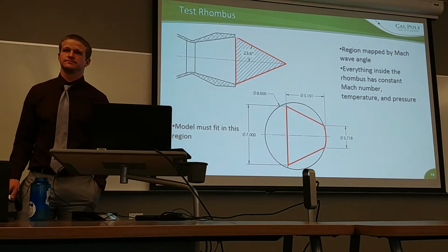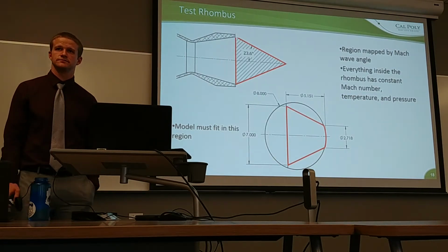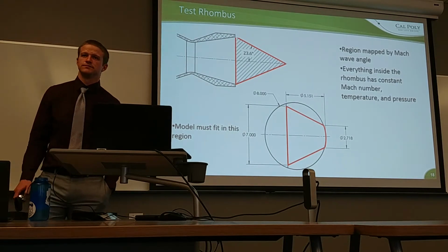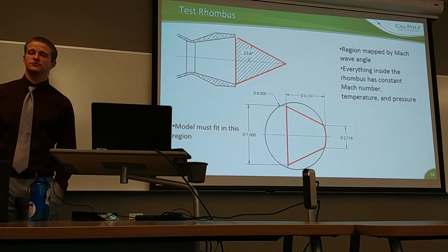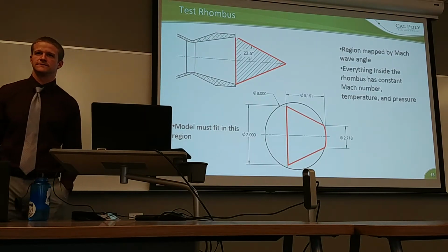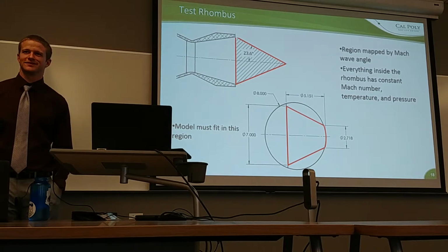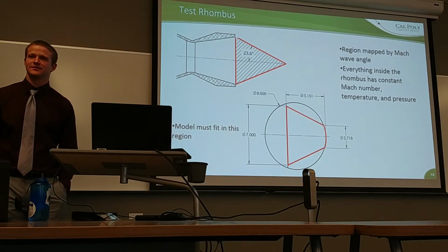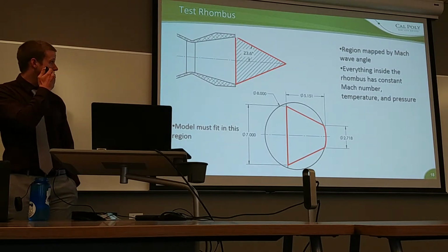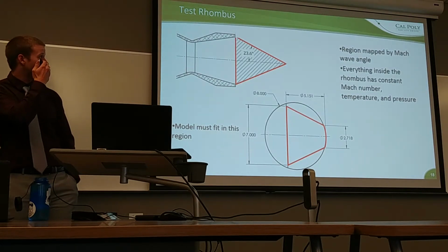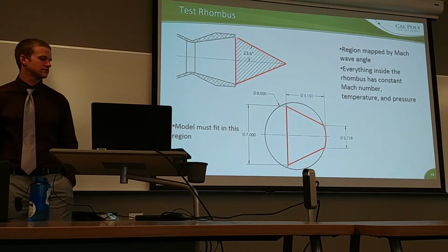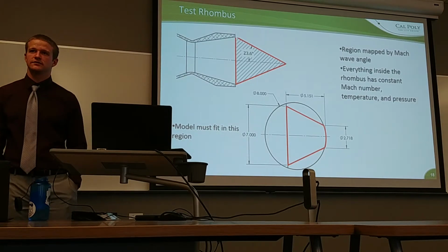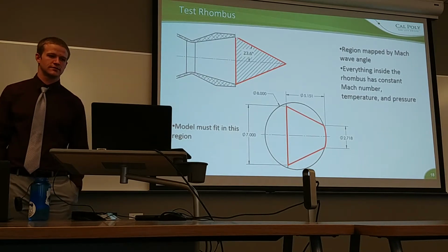Yes. So it's 23.6, the Prandtl-Meyer angle corresponding to the Mach number of 2.44. I was sure it was like 36. Is it really? I looked it up: 23.6 for air at Mach 2.44. So okay, but I think you're correct, you're just saying it wrong. I think you measured 36 probably.